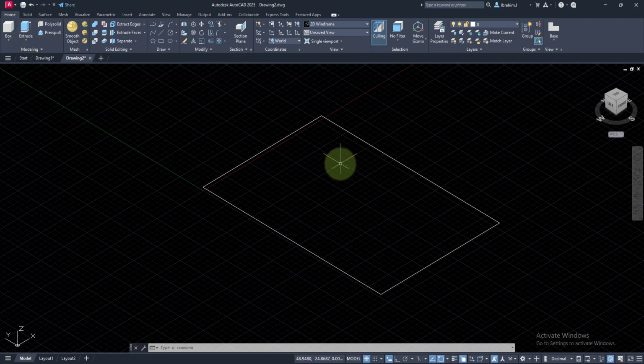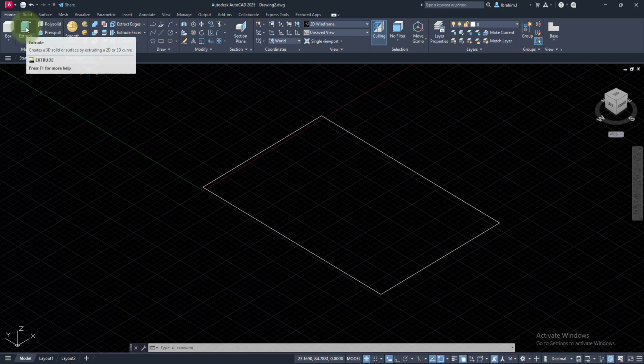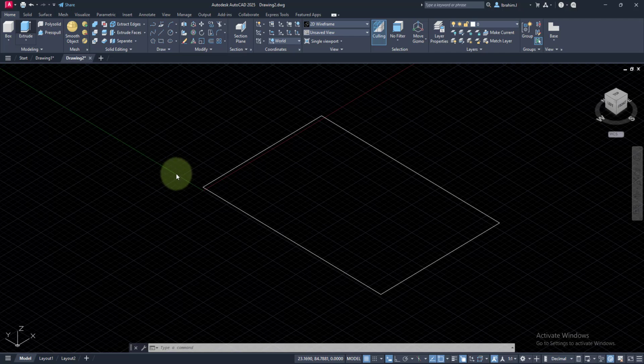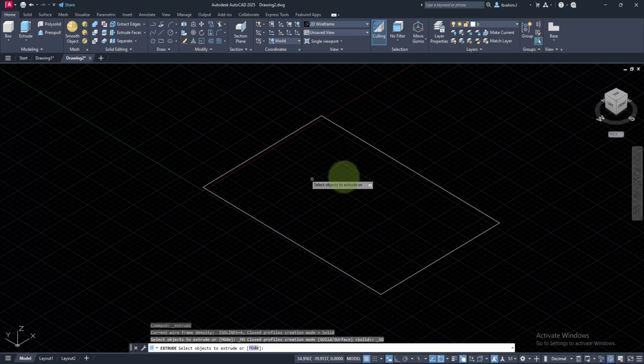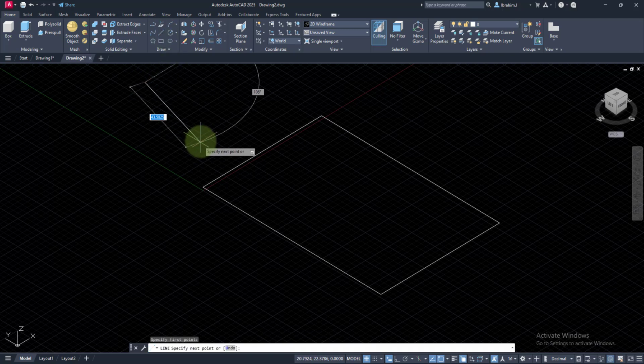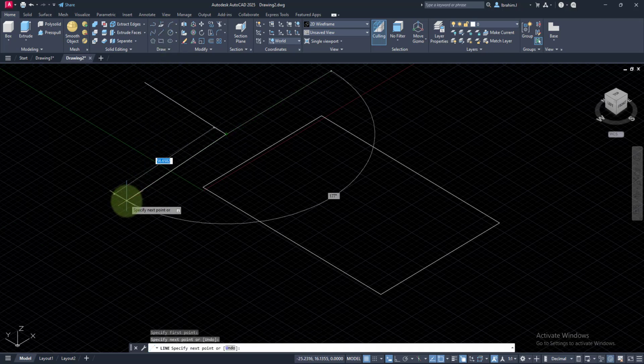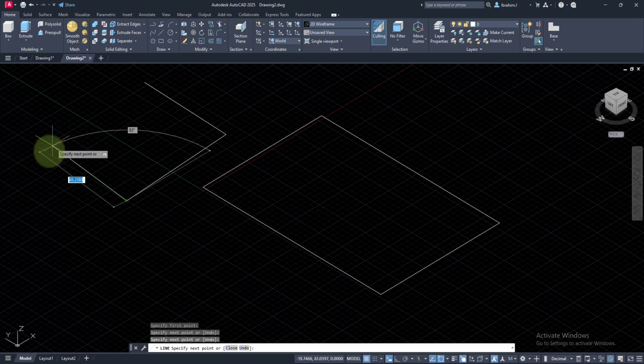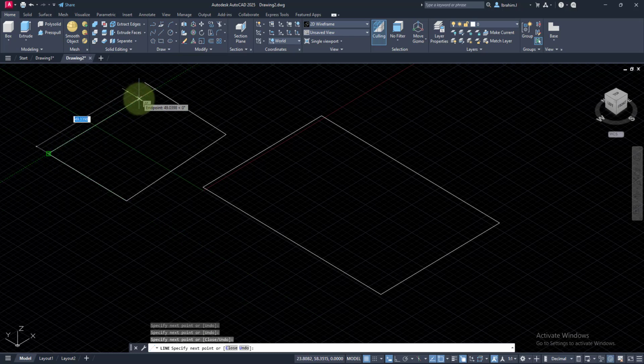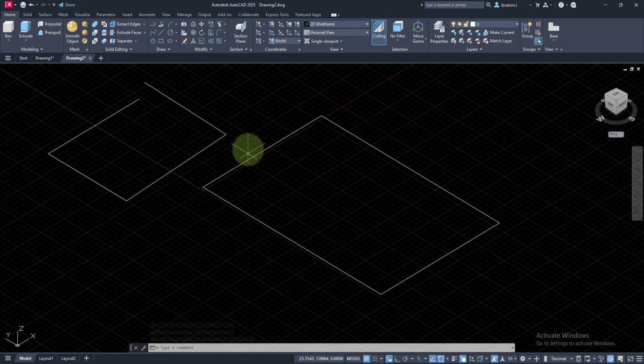All I have to do is, from this sketch, go to extrude. And when I click on extrude, first, if you have a sketch, you know the way you start your extrude. When you want to extrude on AutoCAD, for example, it must be a closed profile. And what do I mean by a closed profile? If it's not a broken line, right? Let me create a broken line for you. Something that looks like a rectangle, but it's not a rectangle because it is not completely closed. When I get to this end and I stop here, this is not a closed profile. You might not be able to extrude this. We can also do some things with this actually, but this is not a closed profile.